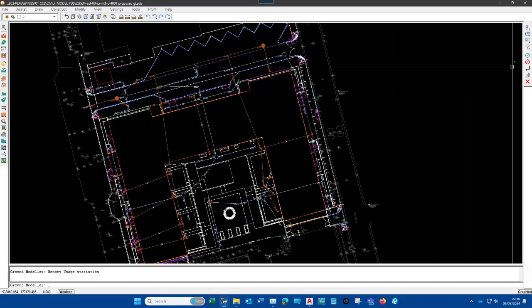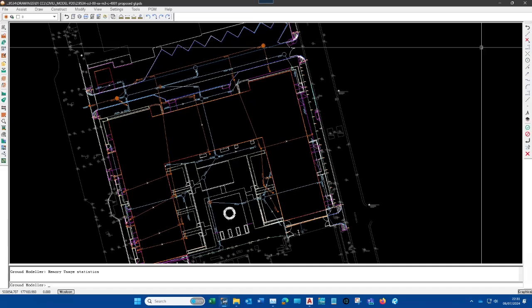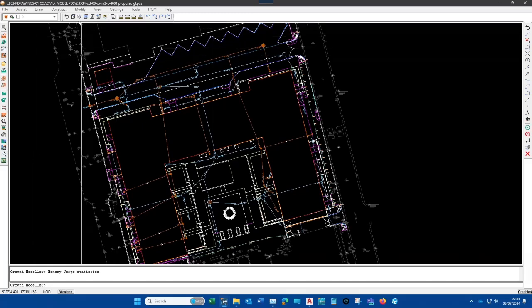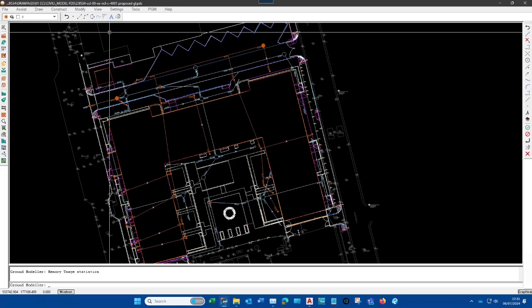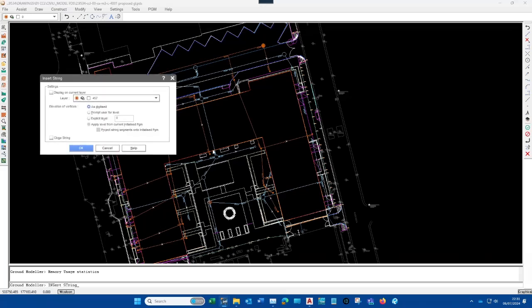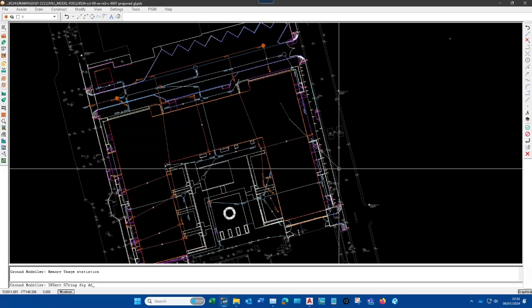So if we come over to the data retrieval command bar, the first one on the list is object snap. This is the same thing as F3 in CAD, your snap settings. If we go to view, toolbars, draw there, instead of going back out to the top and into the draw toolbar, I use that one to go straight to it. And there's string, which is a polyline in CAD talk. We go digitize, click a point, then I want to snap to that line.